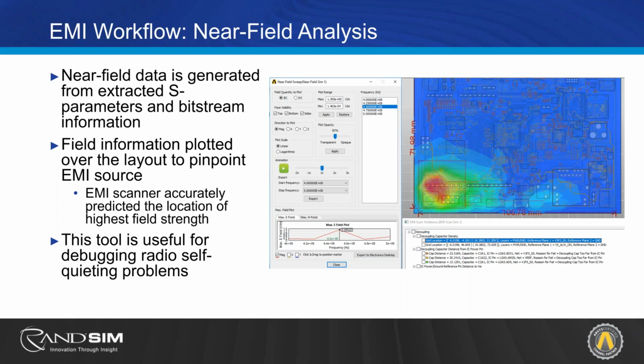You are just using the fields and then allowing those fields to propagate now in the presence of the shield. And HFSS will then compute using the near field as sort of like a seed field, seeding the data. It will then show you the adjusted near field with the shield present. And so it's an additional step, but it's something that can be incorporated within the linkages of those two tools.